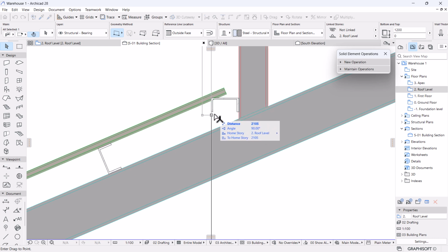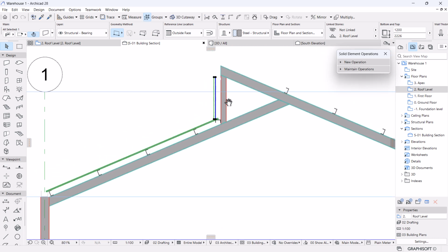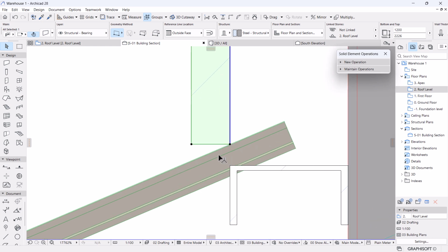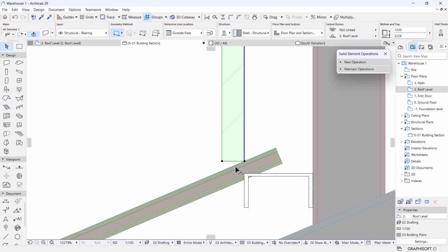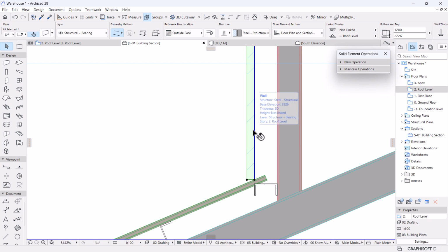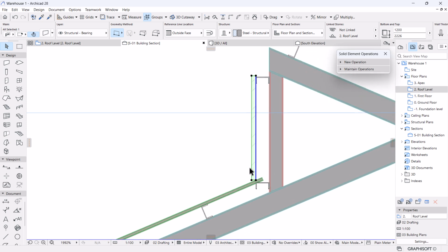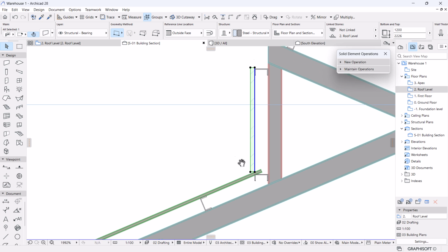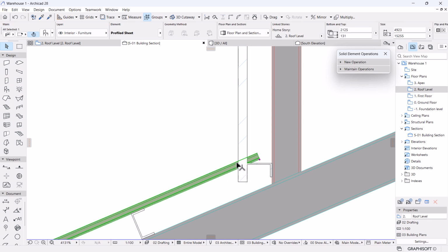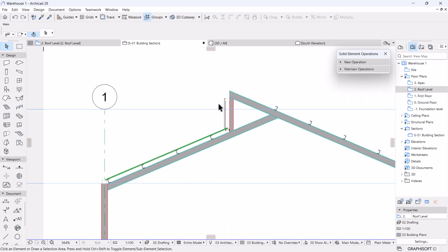Right, I'm gonna position it right on top of our roof. It's always good practice to align things like this, to overlap elements, especially because you don't want to promote seepage of water. So if it's like this, it's better, because when water flows here, it drops around and then flows with the roof profile. Unlike if this was the one that overlaps down and then this stops here, that could create a seepage of water within the roof structure. So always be mindful of that.